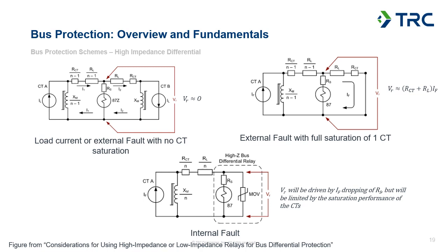So this scheme is monitoring a voltage over that high impedance element. And we can take a look at what that voltage looks like during certain scenarios to determine how we can make a setting selection that's going to operate reliably using this type of protection.